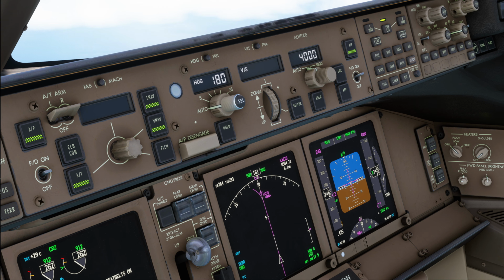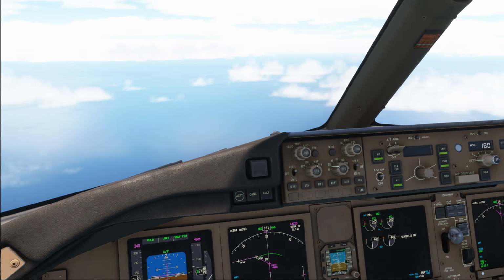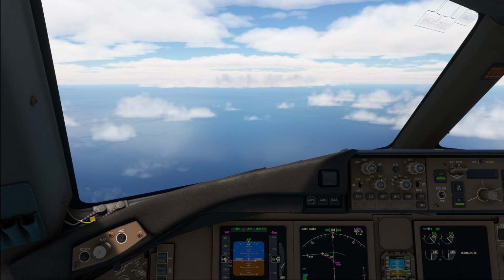Now, automatic flight is the preferred method of flying non-ILS approaches, as automatic flight minimizes flight crew workload and facilitates monitoring the procedure and flight path. During non-ILS approaches, autopilot use allows better course and vertical path tracking accuracy, reduces the probability of inadvertent deviations below path, provides autopilot alerts and mode fail indications, and enables lower RNP limits. Therefore, autopilot use is recommended until suitable visual references are established on final approach.